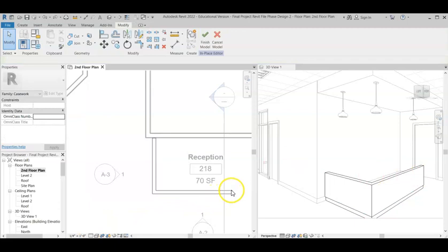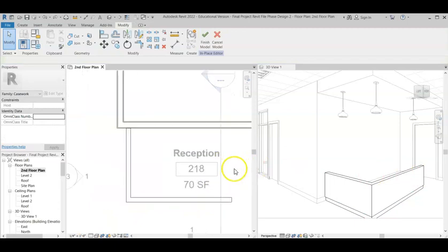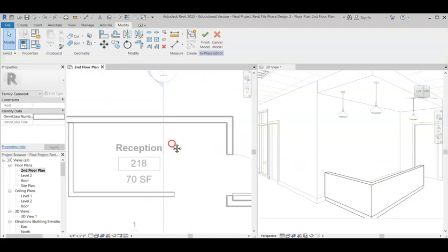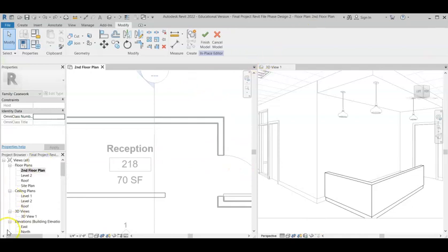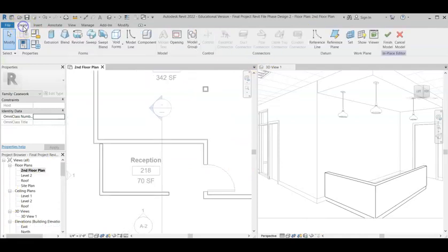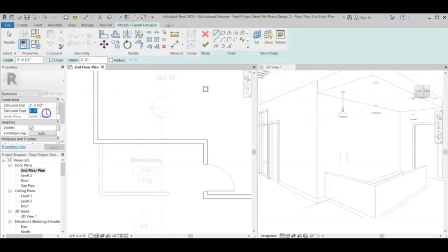The next step is to add a finished end panel on the end of the desk here. So we're going to click on Create, Extrusion. The base height is going to be in line with the bottom of the toe kick, so we'll keep that at 0. And then our finished height is going to be 28.5. So the work surface is going to sit over this end panel.